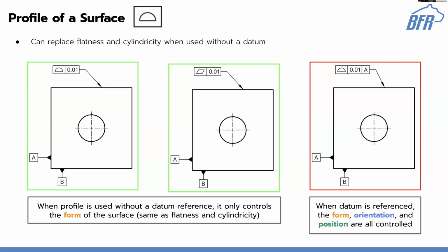You didn't specify it. Most of our sponsors are pretty nice and they know what we want, so even if we give them shitty drawings, they'll accept it. But if you didn't specify any dimensions regarding those cutouts, they don't have to include them, and that would match your drawing specifications. So we throw in a general standard: if nothing else, it should be within a certain profile tolerance of the CAD, and that just saves you some headache.